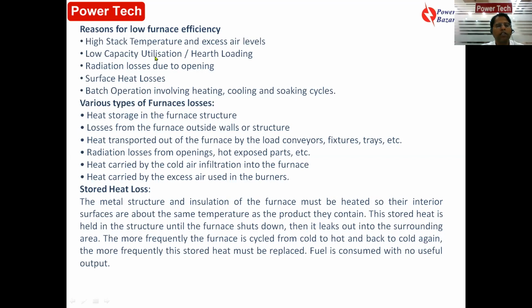Low capacity utilization, harsh loading, radiation losses due to openings. If you keep on opening and closing the furnace, then there will be some radiation losses. Surface heat loss also will be there. And sometimes if you are doing batch operation, that means putting some material, heating, cooling the furnace, and again after some time heating, there will be furnace uptime and downtime, due to which there will be heating, cooling, soaking cycles. And particularly during the cooling cycle, the furnace will lose a lot of energy.